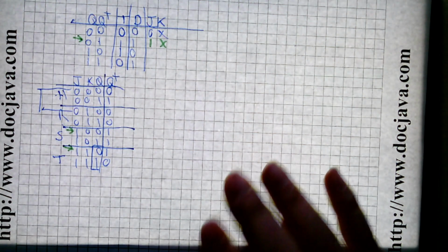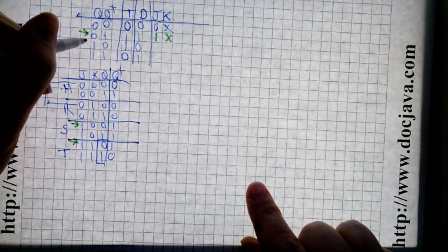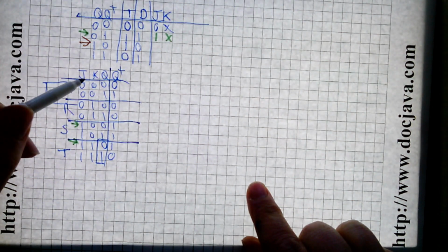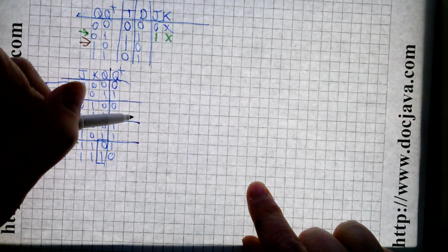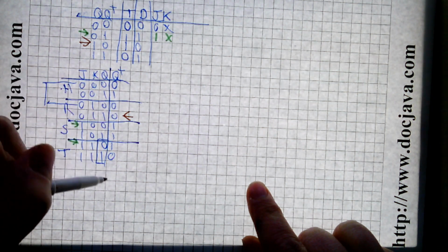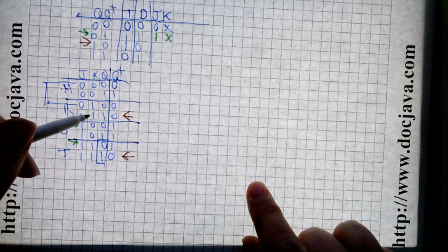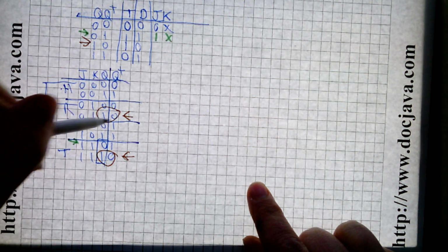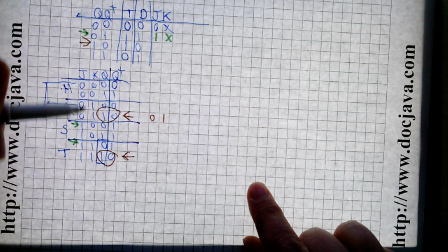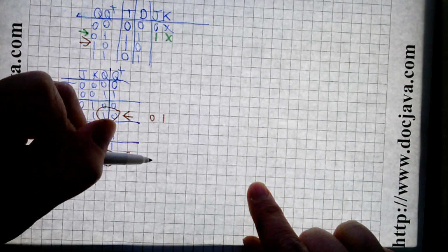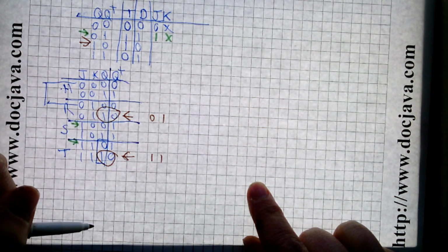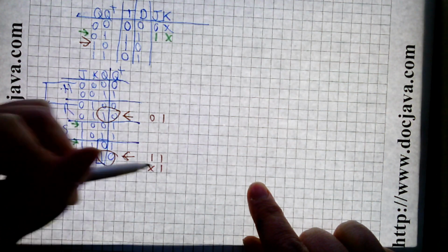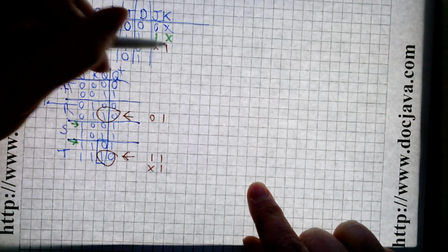Let's try that one more time. This time we're going to do a change from 1 to 0. Right, that's in here. 1 to 0. So how do we do that? Well, that's here, and it's here. And so going from 1 to 0, here and here, means we got our choices. We can either input 0, 1, which puts us into the reset state, or we can do 1, 1, which puts us into the toggle state. And so that means we have a don't care 1. So here's don't care 1.